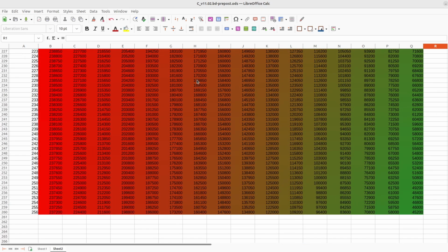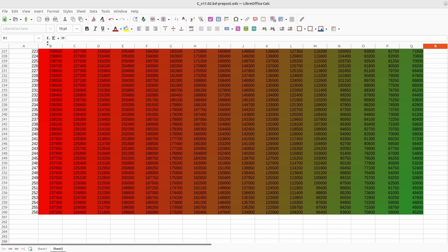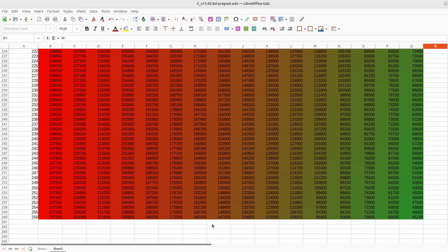And the values inside this matrix represent the error that we would result in if we took that prescaler, the count, and the postscaler, which are all included in this calculation. And our intent is to get this value as close to 0 as possible. So I applied a color shade based on that value to get us close to 0. And we can see based on these values, the closest we can get is 45,000, which is still too far off.